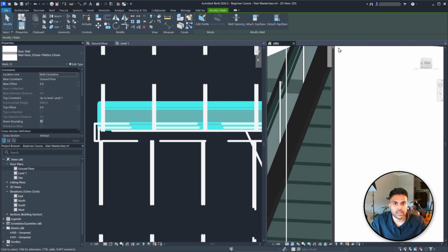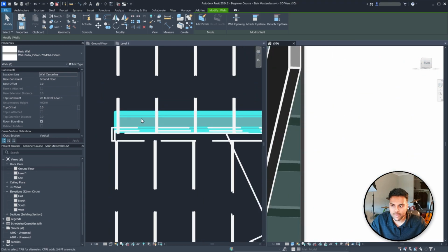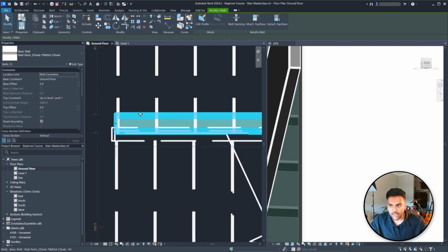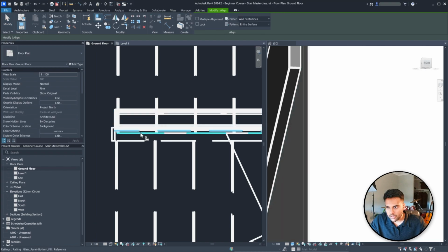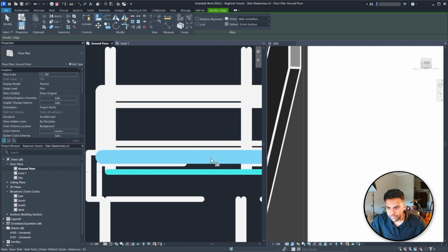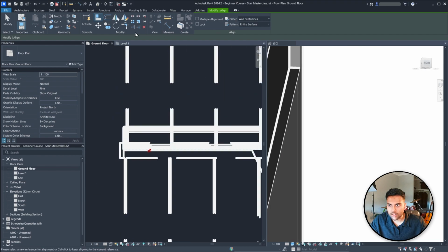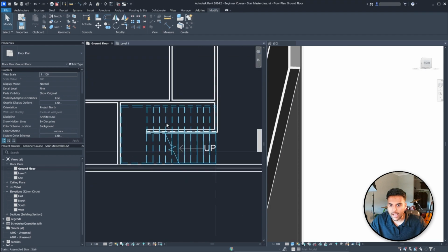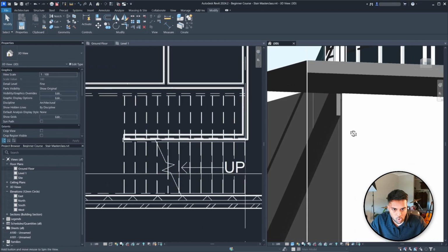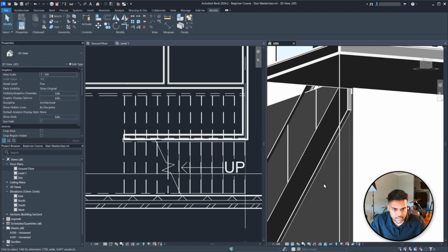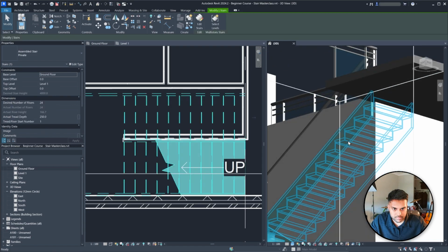So I'll open this 3D view so I can have a look and see what's happening. If I go back here, you'll see that that's about the time when both right supports are engulfed, right? So what I'll do is align my wall to that part, and I'll click, and exit out of my editing mode. So as you can see, that wall is sitting on the right support.